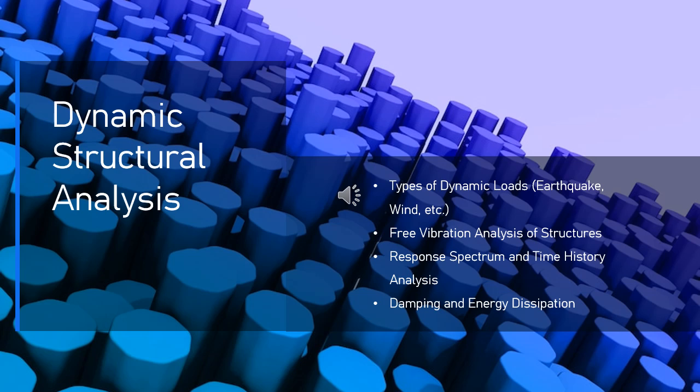Key traffic load types. 1. Point loads represent individual vehicles or trucks passing over a bridge. 2. Moving load. As vehicles move across a structure, their position and load distribution change. Influence lines are often used to model this type of dynamic load. 3. Impact loads. Traffic impact loads occur when a vehicle moves over a bump, pothole, or sudden change in the structure, causing additional dynamic forces.